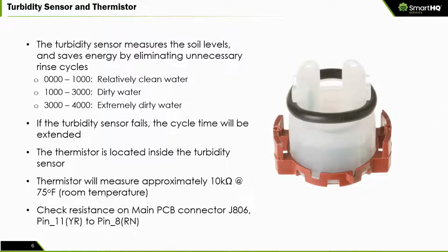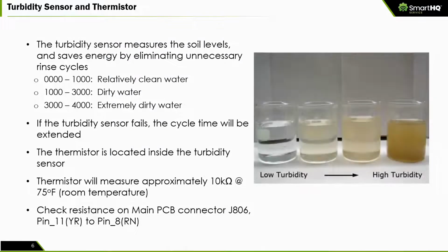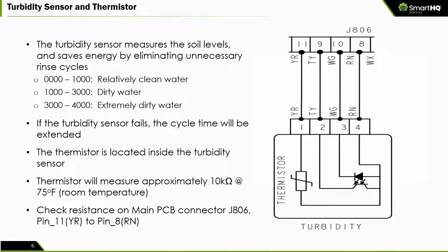Also inside the turbidity sensor, you do have the thermistor. That temperature sensor, that thermistor, is right inside of the housing of that turbidity sensor. So guess what? If you need to replace your thermistor, you are replacing your entire turbidity sensor and vice versa.